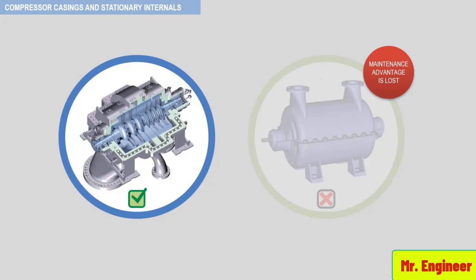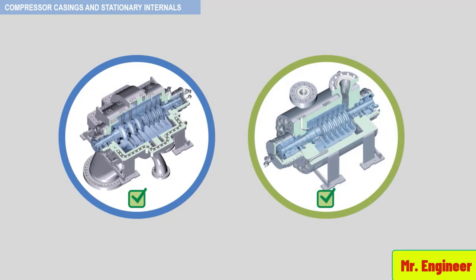And when performing your cost analysis, be sure to include the cost penalty for the additional removal and assembly time for top-mounted piping. Also, be sure to include the revenue lost per day of additional downtime if the compressor is unspared. Just for your information, typical additional times for piping removal and assembly are around 2 to 3 days and sometimes longer. So if the cost is prohibitive, another option would be a barrel compressor with top connections, as depicted in this example.